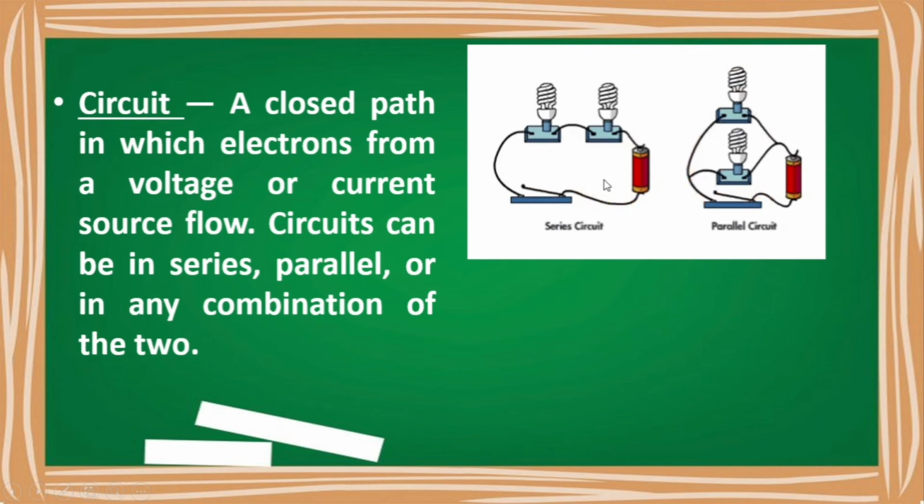The disadvantage of the series circuit is that if any of these elements is not working properly, it will not let the current flow in the rest of the circuit, hence opening the circuit. Whereas in the parallel circuit, if one of these elements does not work well, still the bulb will glow.